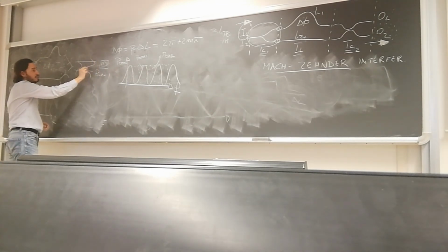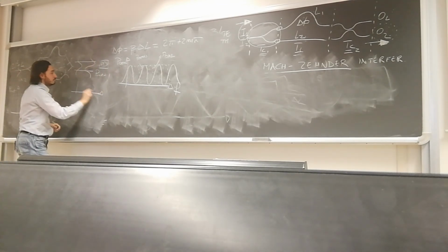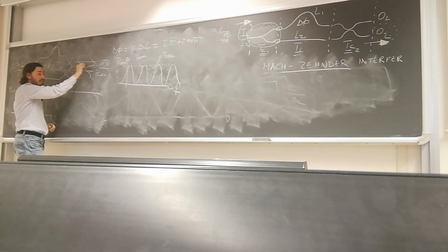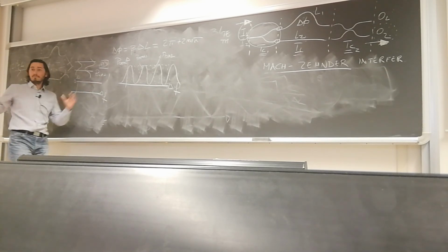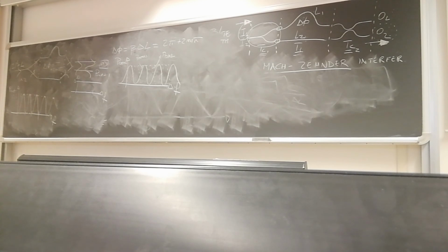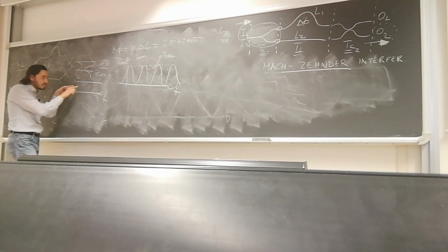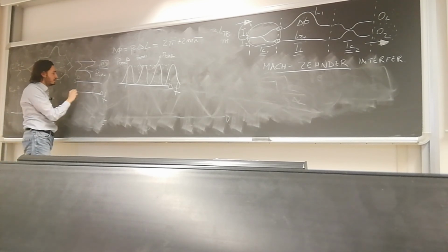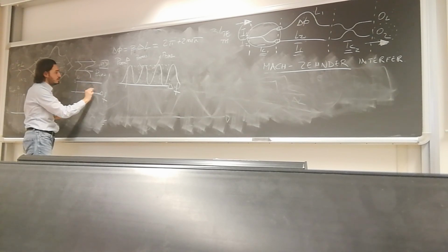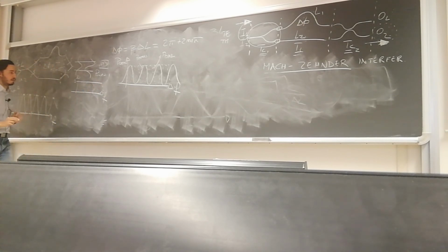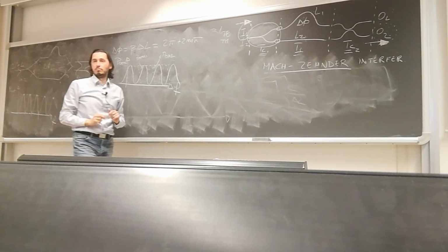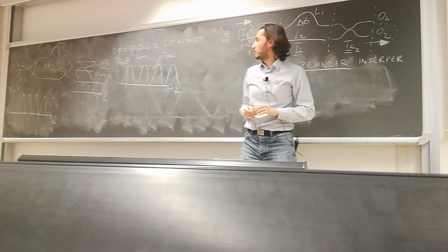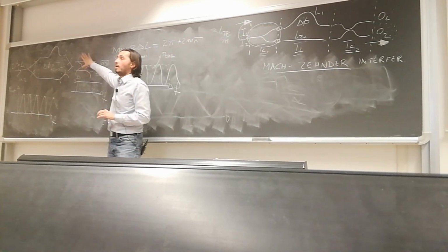So in this case, if the waveguide is multi-mode, whatever the frequency, my photodetector will see 1, if the photodetector is able to catch everything. But if I look inside this power, I will discover that there are some frequencies where this power is carried by the fundamental mode, other frequencies where this power is carried by the second mode. So I'm swapping the power from one mode to another mode.